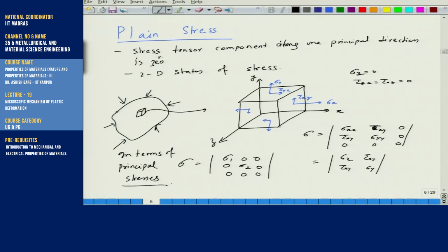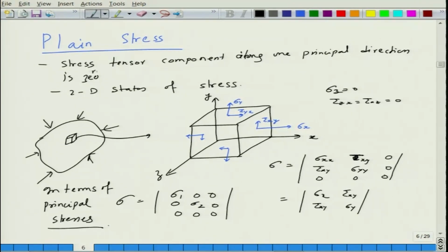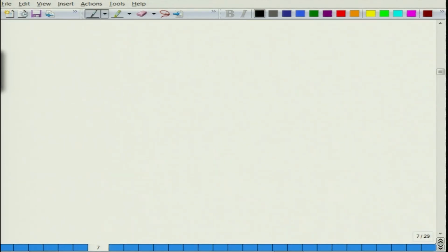So, this is the stress states. We should have ideally discussed this in case of elastic deformation, but just to introduce the states of stresses. Alright, so this is what it is in terms of plastic deformation, that you have formation of a neck at UTS, sample undergoes non-uniform deformation, there is a cavitation at the UTS point, and as you stretch the material further, those cavities coalesce or merge into each other, forming a bigger cavity, which sort of leads to rupture of the material at 45° roughly to the tensile axis.